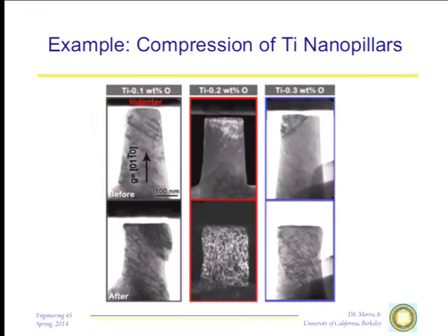Here you see dislocations in the material; they tend to move along 45-degree lines where the shear is maximum. We'll talk about that in just a moment. Particularly as you get the solute content up, so it becomes harder to move the dislocations, the material becomes quite a bit stronger. The deformation produces real tangles of dislocations, such as you see here. This is the phenomenon of dislocation hardening or work hardening that we'll talk about in just a minute. But we can now observe the behavior of dislocations and follow it. We can do both tension tests and compression tests in the transmission electron microscope and actually see what's happening. And that's done on a regular basis in Andy Minor's group up at LBL.